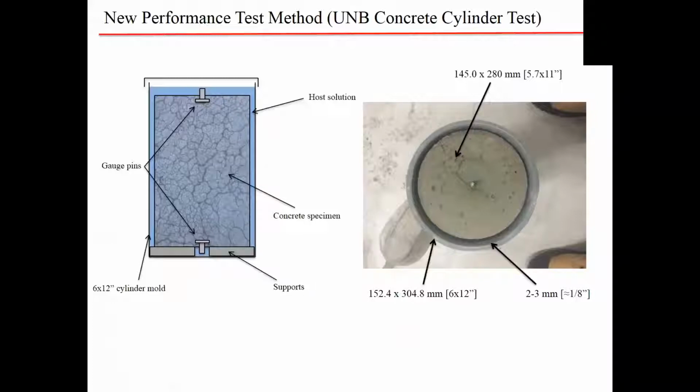And the other important consideration here is the actual amount of external water is in the region of about a quarter to a third of the actual amount of pore solution. So you're trying to combat dilution anyway by designing the surrounding solution to be the same as the pore solution, but also you've got a very small amount, enough to fuel ASR because you keep topping this up, but you're not going to lead to significant augmentation of the alkalis or significant leaching of the alkalis.